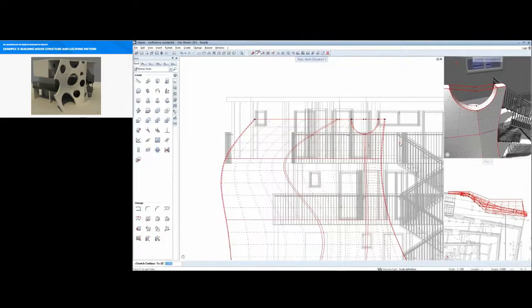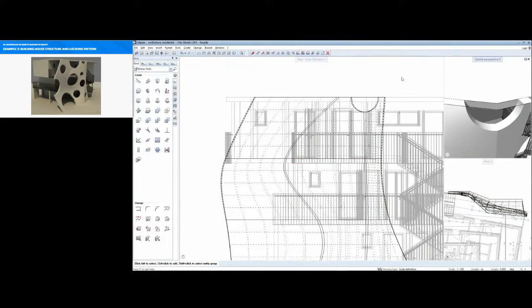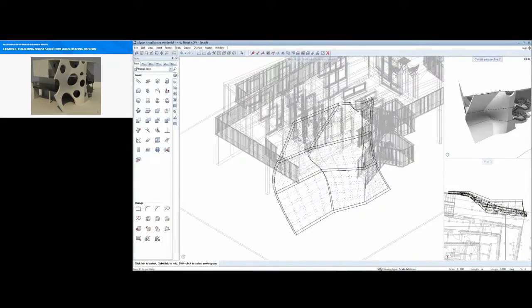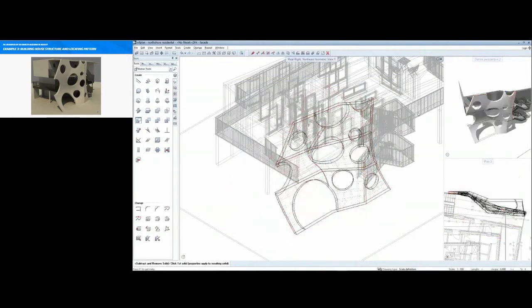Aside from the adjustments described, other modification options also exist. For example, you can realize the Boolean operation by subtracting further cylinders from the loft object. The Boolean operation can be realized as soon as the cylinders have been created. All the other cylinders are now subtracted from the loft solid. What remains is the desired facade design.